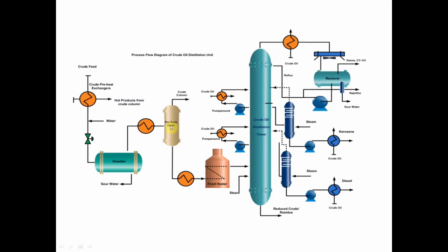Okay. So the crude oil is taken to the pre-fractionator or pre-flash drum fractionator, which means the vaporized products are taken out from the pre-fractionator column. I said this, the lighter portion of the crude oil, the fuel gas, LPG, and some other naphtha, those are taken from the pre-fractionator unit or the column. And the bottom material of the fractionator unit is further heated and taken to the furnace.